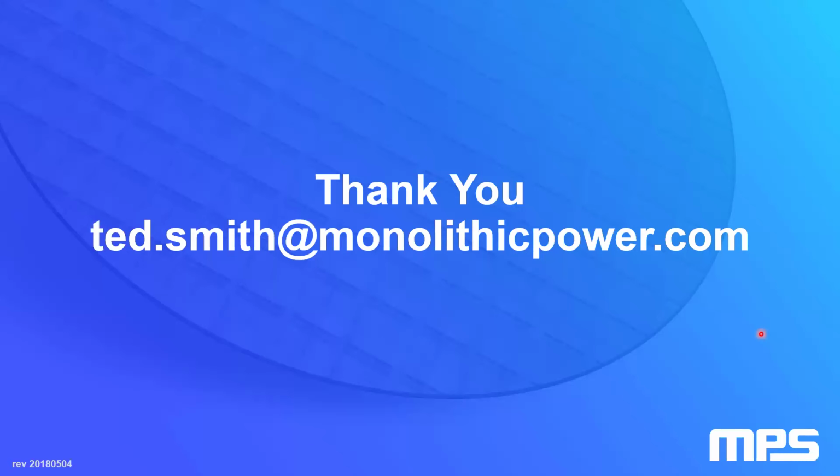Ryan says, please consider adding SENT output to your 3D sensors. Aha. This is not the first time I've heard this, so I really appreciate that kind of feedback. It's single edge nibble transmission, I believe. For the automotive guys, I've heard this before, and this is something that we are in fact working on. I don't know if we're working on it in the context of the 3D sensors, but we do have position sensors that we're working on with SENT.